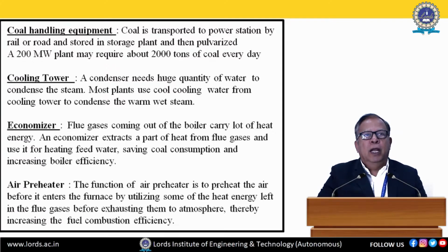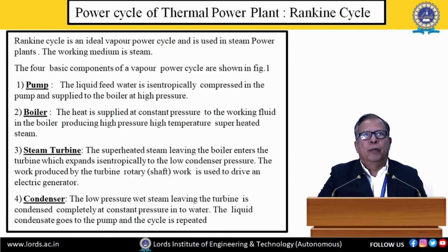Then what is air preheater? The function of the air preheater is to preheat the air before it enters the furnace by utilizing some of the heat energy left in the flue gases before exhausting them through the chimney, right? Thereby increasing the fuel consumption efficiency. So air is required. Oxygen in air is required for combustion of fuel.